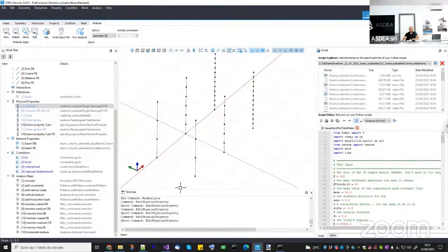It is a bending problem. So the curvature will be anyway. Once again, I do the drawing. In this case, I'm applying a force here. So the distribution of the bending moment is here. So it is not a constant state of deformation. The solution knows that these elements here are the ones that are going to localize first. So there is no problem of bifurcation of the solution in this kind of problem. So it is not necessary to put imperfection just for triggering localization. The localization will trigger anyway. So we can get rid of the point now.